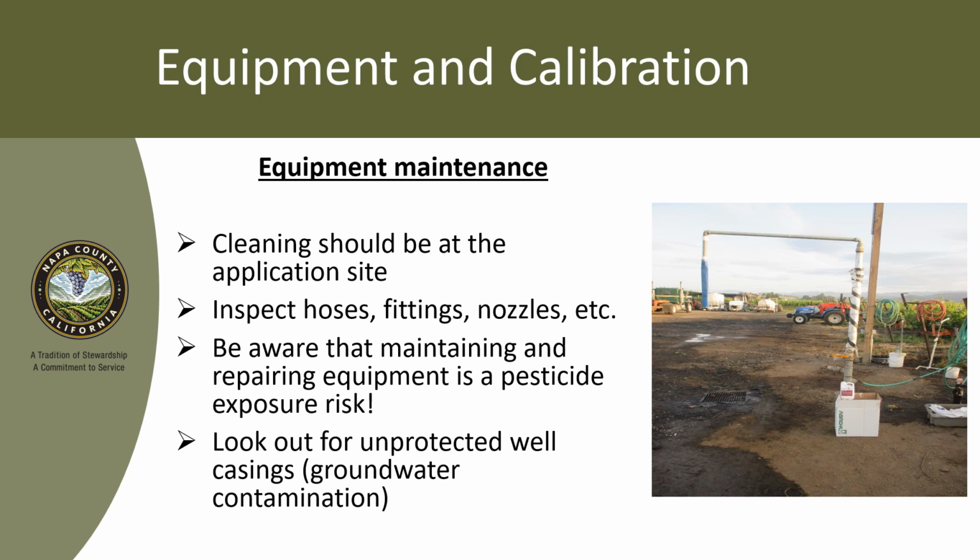Now, if you take a look at that picture, you'll notice it's like a stanchion that comes up, hits a right angle, and then there's like a hose coming down. What is that? Hopefully, most of you know that that is a manual air gap. So the tractor pulls underneath that, and they open up the tank, and there should be a nice separation, an air gap between the end of that hose and the upper rim of the tank. The reason that we have that is because we don't want pesticide that's in the tank or any kind of mix at all to accidentally backflow back into the freshwater system.